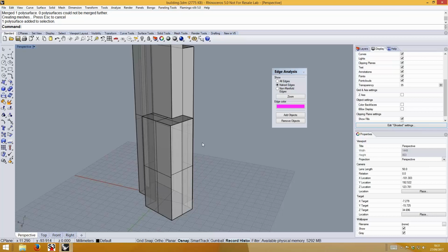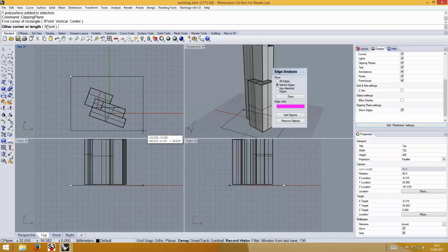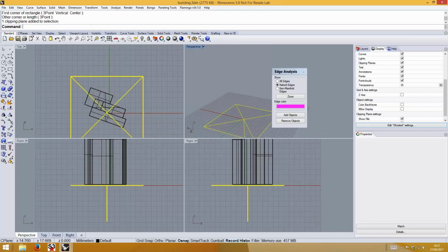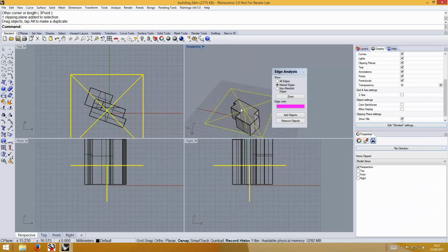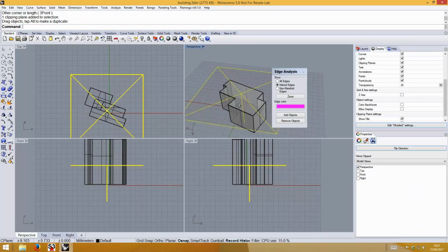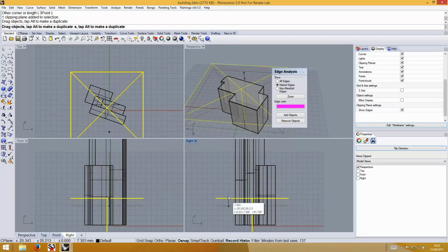And before doing that, I would like to show you another tool that will be quite helpful in these cases, clipping plane. Okay, the clipping plane will let you define a dynamic cut plane that we can use, there you go, sorry, to analyze what's going on and see if we're having a single section, or a single skin, better said, on the file.